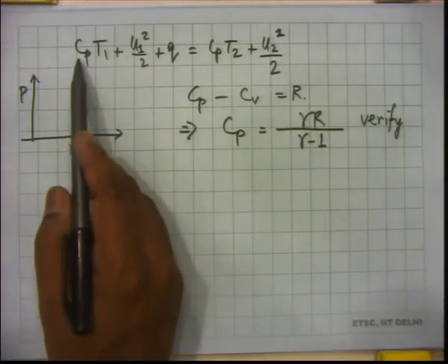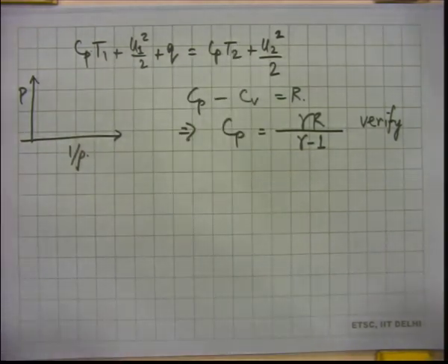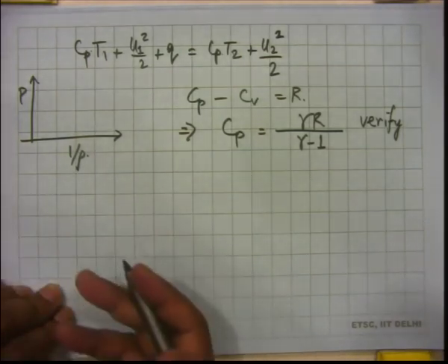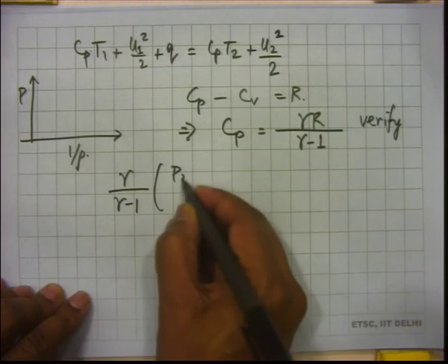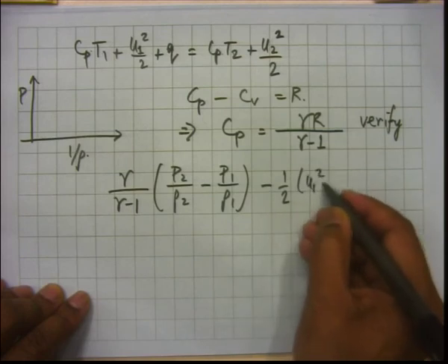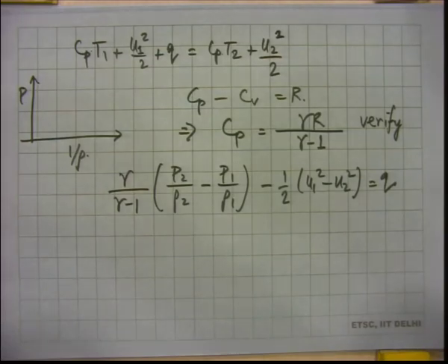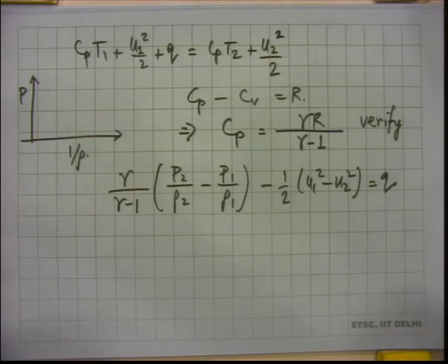So, for this Cp, if we use gamma R divided by gamma minus 1, then you will get RT1 here and RT2 there. Okay. Actually, R1T1 and R2T2. And then we can replace R2T2 as P2 by rho 2, R1T1 as P1 by rho 1. Do that. Then this can be obtained. Jumping steps, as I told you. They can verify, not here, maybe at home.